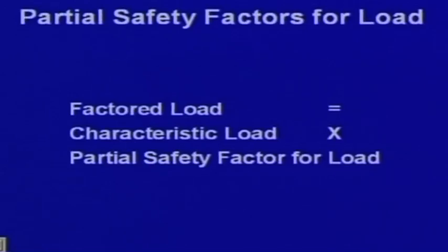The partial safety factors for load. So, factored load: we do not only check the load you are getting. In our limit state design, particularly, that load is multiplied by a certain factor, which gives you the factored load or the design load.